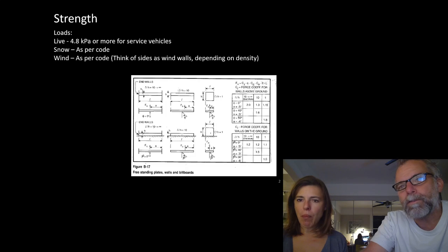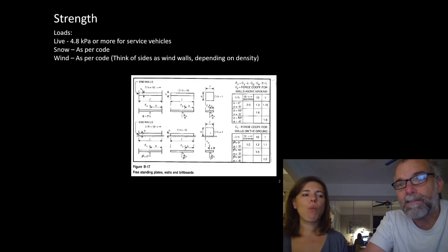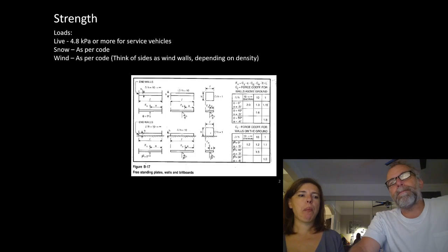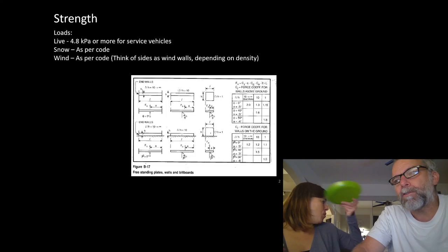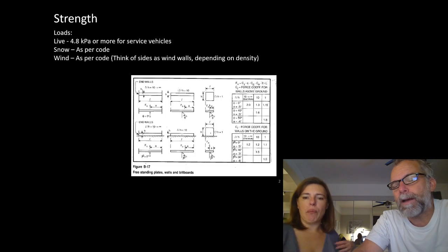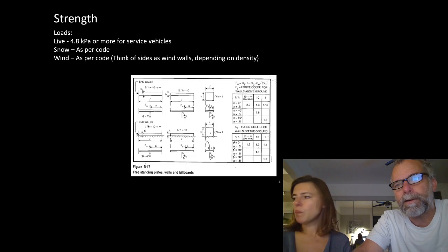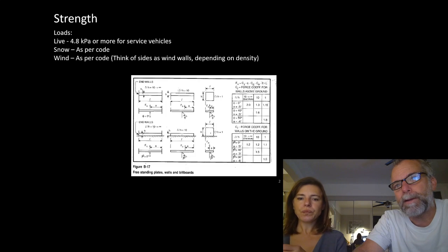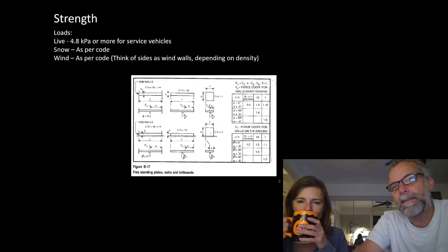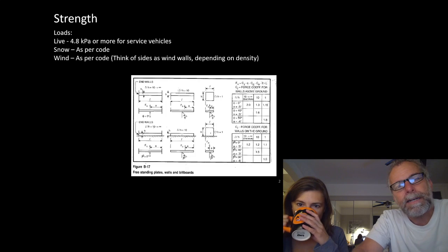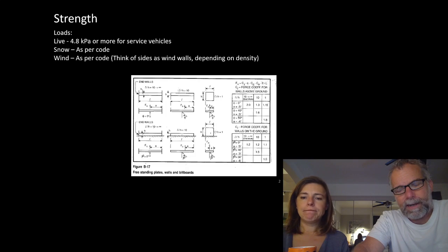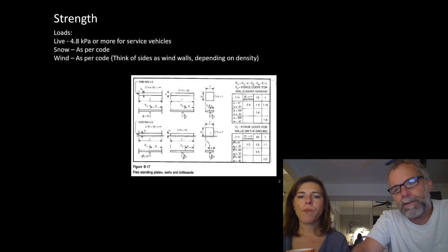The Q, which is your reference wind pressure. CG, which is your gust factor. So we are measuring hourly mean winds, but the hourly mean wind is not representative of the peak wind. So we multiply by a gust factor, an exposure factor, which accounts for context, height above the ground, for example.